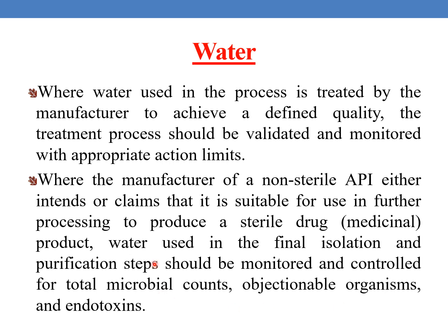Especially in the case of water for injection, you need to take these points into consideration: microbial counts, objectionable organisms and endotoxins.